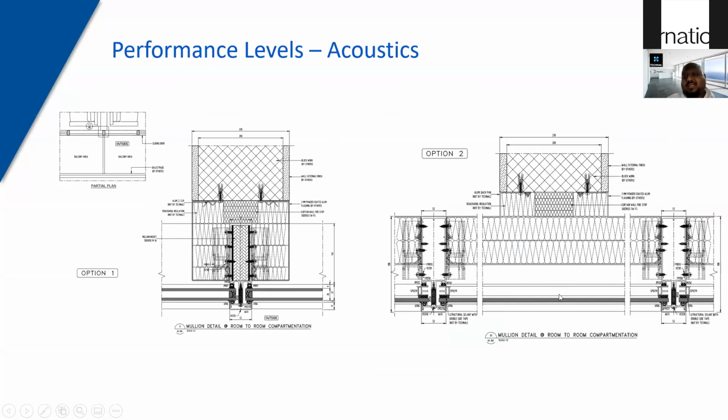Another good strategy is, and this is where again early engagement with the supplier to really define the grids, when you have situations like this, to go for what we call a split mullion. A split mullion is more cost effective because you don't have to spend so much money insulating your mullions, but by creating this natural space, you're able to not only save money, but also create a simpler detailing when it comes to construction.